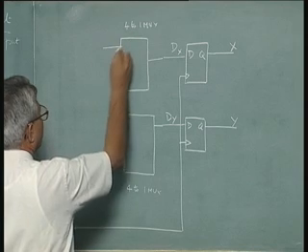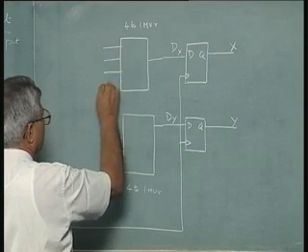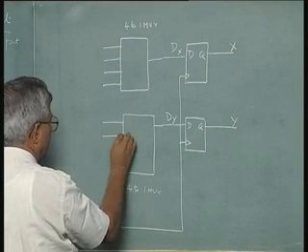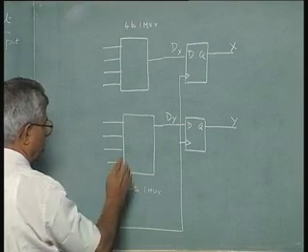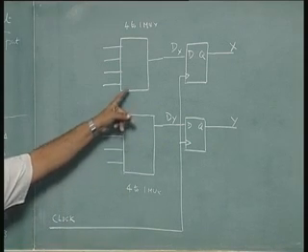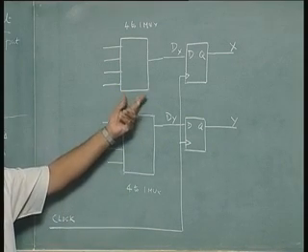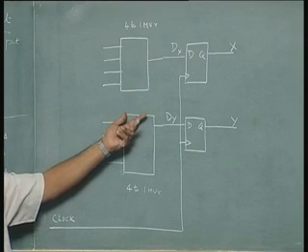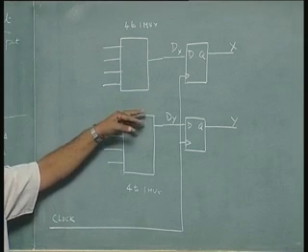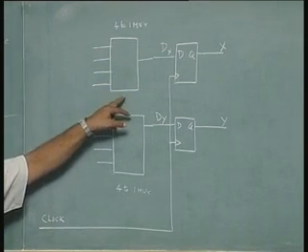The inputs to these muxes come from the conditions that we impose for changing from state to state. Corresponding to each state, the multiplexer selector inputs are decided by the present state, and the next state is decided by the input that you give to the present state.